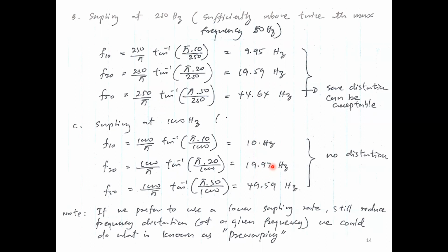All right, so we have learned a lot on that. Simple satisfaction of the Nyquist theorem is not good enough if you have to look at the signal warping due to numerical integration and any other numerical discrete signal processing. As a result, you need to increase your sampling frequency way beyond the Nyquist limit.